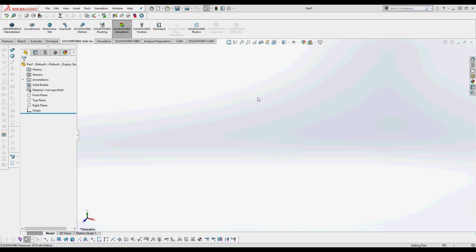Okay, so today we're going to be looking at how to do basic composite simulation in SolidWorks. This is for the MSE398 Composite Tube Design Competition. So first thing, you're probably familiar in SolidWorks with what we call solid geometry, which is three-dimensional shapes that have volume. For this project, though, we're going to be using what we refer to as surface geometry. So we're just defining surfaces that are still three-dimensional, but they have no thickness. And we're going to be using that to define our geometry and to run our simulation.